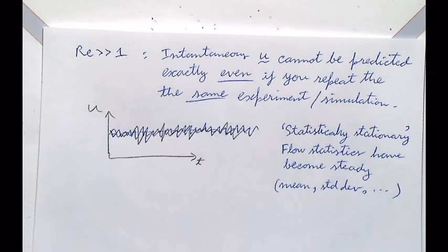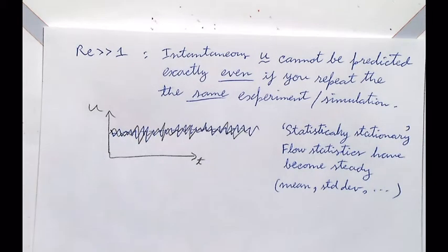Again, we've talked about this, you've told me this, but in the experiment, where is it? So you said the small perturbations can change the flow field, right? In the experiment, where do these perturbations come from? For example, if you're doing this in the hydro lab, where is this perturbation coming from? That comes from, for example, the environment. Yeah, if you're running an experiment with a flow, the floor might be vibrating because there's a truck outside passing by. There are very small fluctuations in the air.